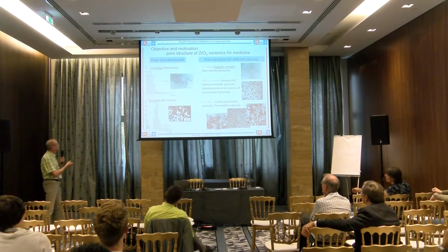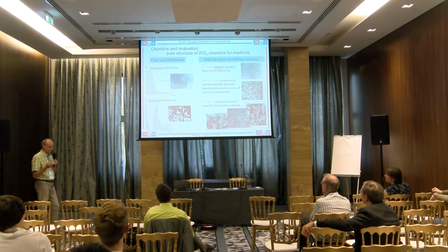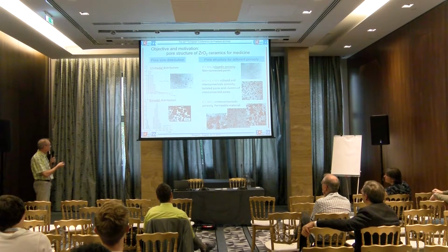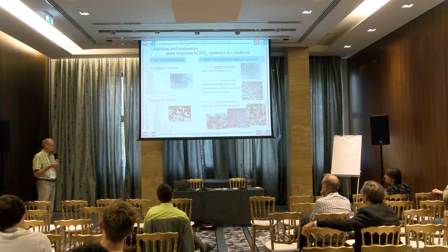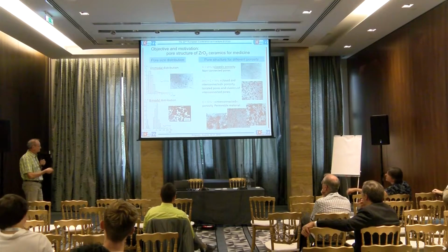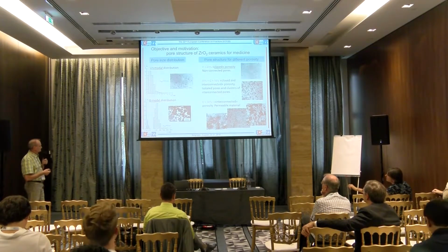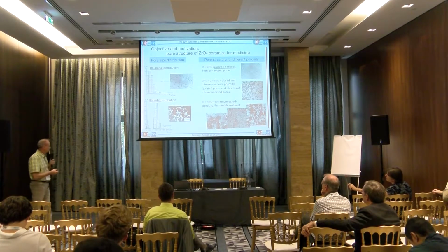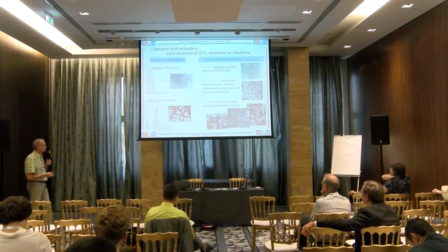A specific feature of these ceramics in this medical application is that they have a multi-scale structure. Initially, when you produce ceramic, it usually has unimodal distribution of pores, but for medical applications you have to use special fillers from organic materials to produce larger pores. So we have two parameters for pores, small pores and large pores.